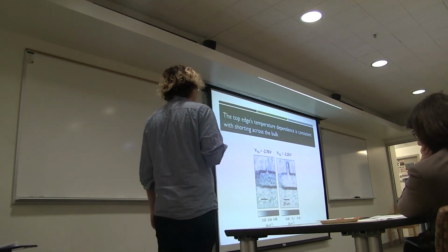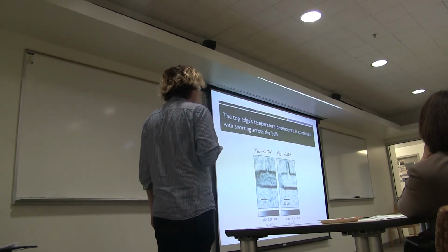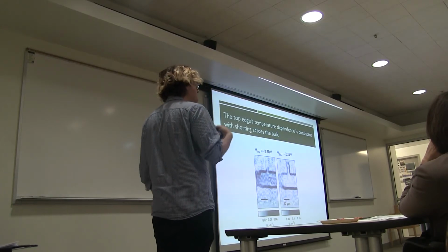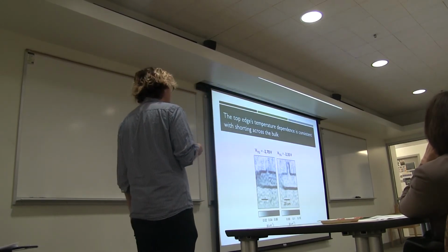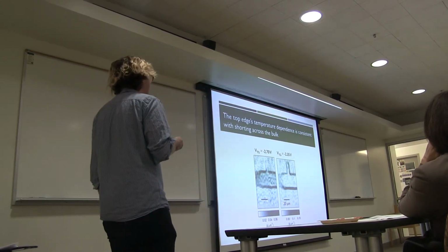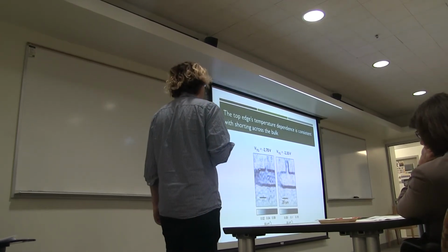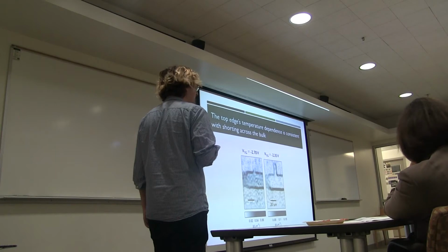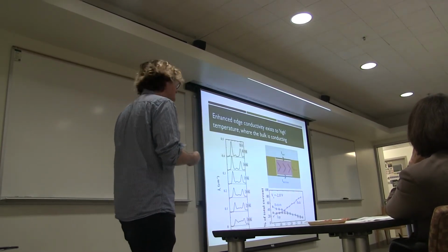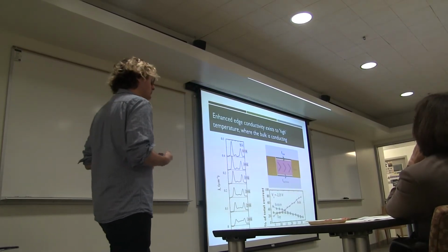We have these voltage leads here, and there's a very small amount of bulk material here. If the bulk begins conducting, current can either go all the way up the edge and across, or it can jump across the bulk. So once the bulk starts conducting, these voltage lead edges are shorted, and the effective length of the edge where current is flowing is halved, and ends up being approximately the same length as the bottom edge. This is the reason why we see this asymmetry at low temperatures when the bulk is insulating, and then they join together at higher temperatures when the bulk is shorting them.